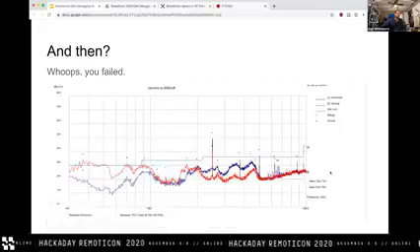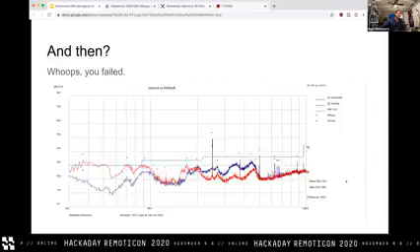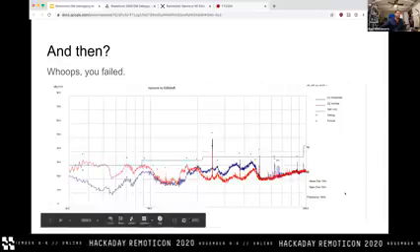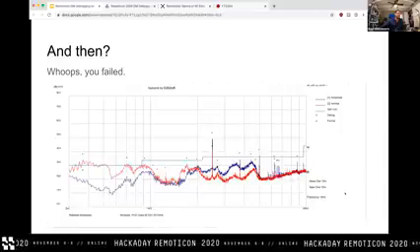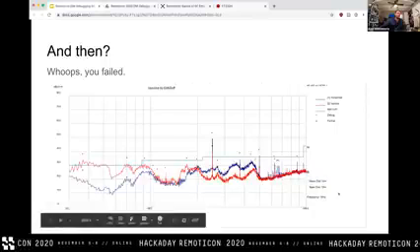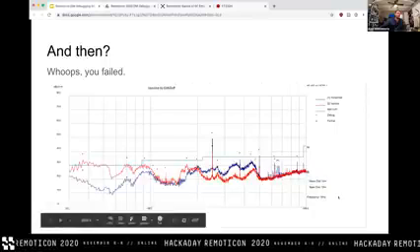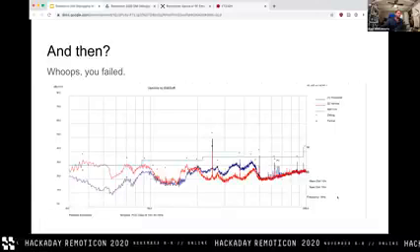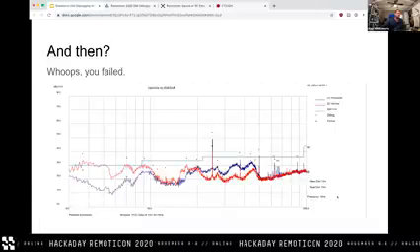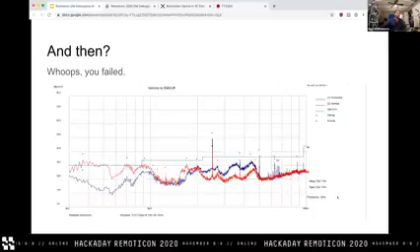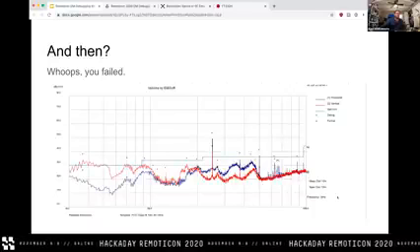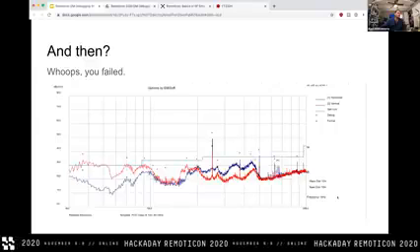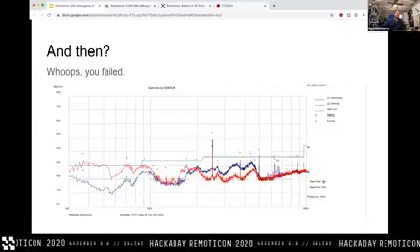So let's look at what this report is actually saying from the get-go. First things first, there are a couple of different standards for testing. There is measurement distance and which range of spectrum you're trying to measure. So in this particular case, this section of the test report is covering the frequency spectrum from 30 megahertz to 1,000 megahertz, the sub-gigahertz region. And this is specified at 10 meters.